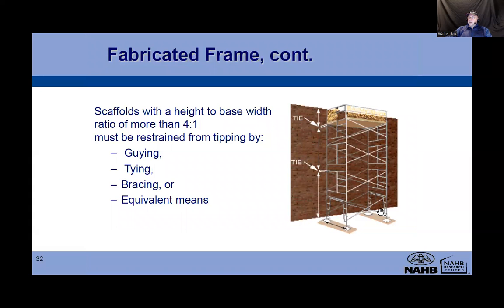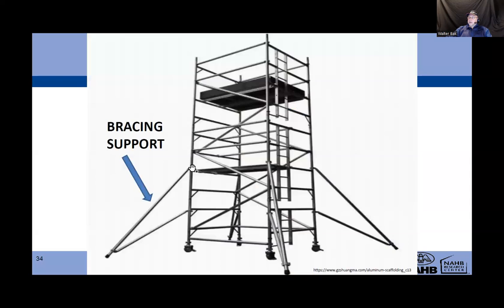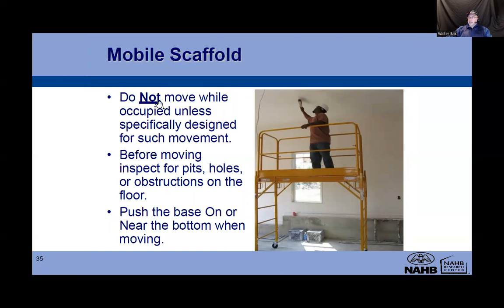There's cross bracing, and there's bracing. Here's bracing. Remember the center of gravity. By bracing, you are extending the area of the base. So if there's a center of gravity, you can go further with it. This is preventing the whole structure from tipping, and it gives extra protection compared to just having the base. Because remember the safety of the center of gravity: if the center of gravity of the whole structure goes beyond the base, then the structure tips.